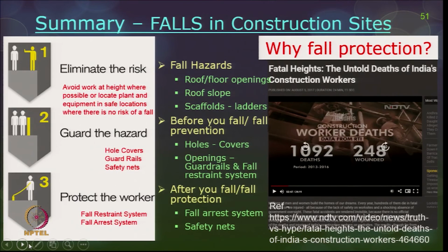These are all passive protection, or I would say environment protection. So, workers can work even without proper PPEs, still they will not have a fall hazard. Number three, as a double precaution, protect the workers, primarily with PFAs in place, which can be in terms of a fall restraint system or fall arrest system.